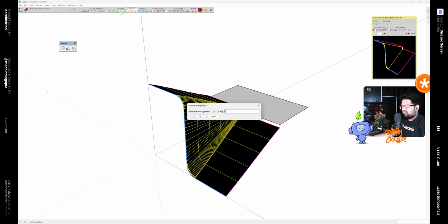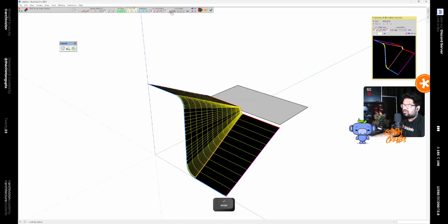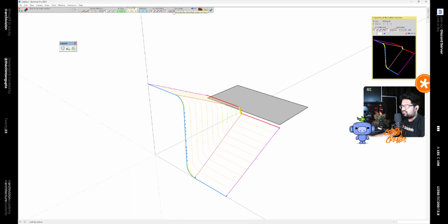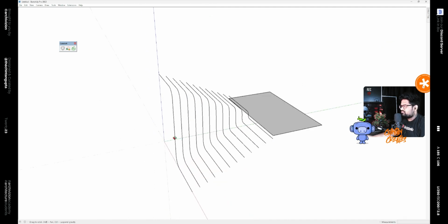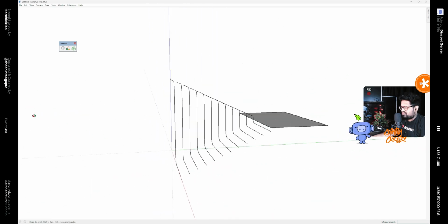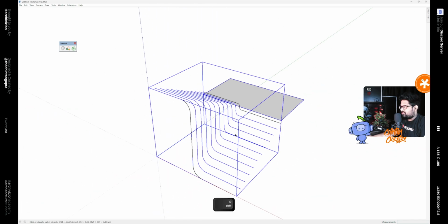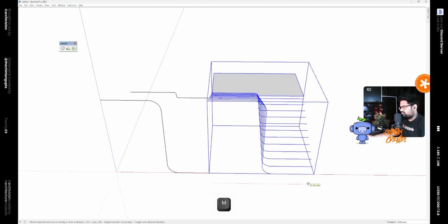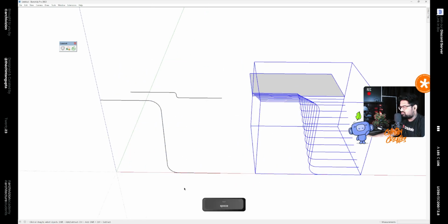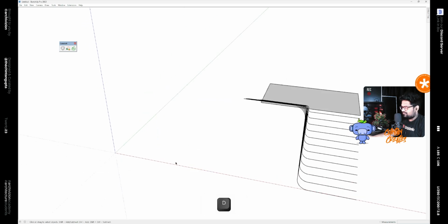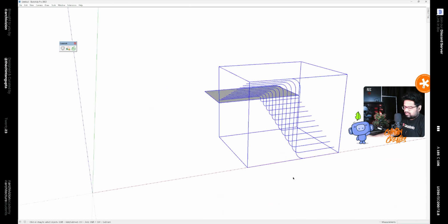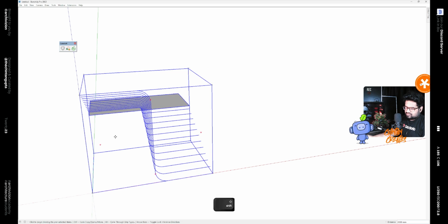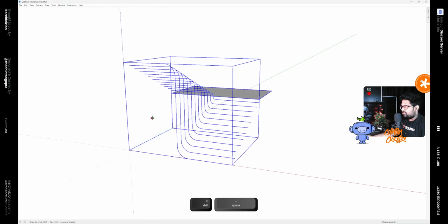After that, turn the number of segments to 11, and we don't want the mesh, we only want the segments to be made. So click on this button over here that says generate the intermediate edges, no face. So we have these edges. After that, select these and move them aside by, let's say, 6 meters, so that we can delete these and then move them back in place. Close the curve loft plugin.